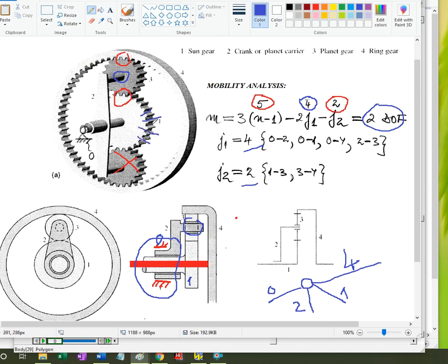So ring gear, sun gear, or you can fix the carrier, but if you fix the carrier, it turns it into a fixed axle transmission. Although possible, in automatic transmissions some of them may have combinations where a unit turns into a fixed axle transmission. Okay, so analyze for mobility.